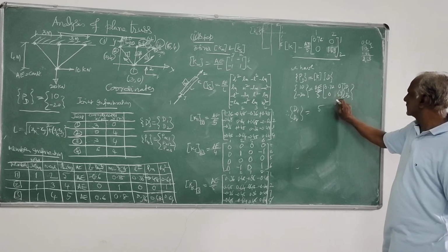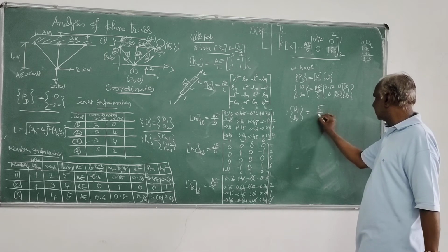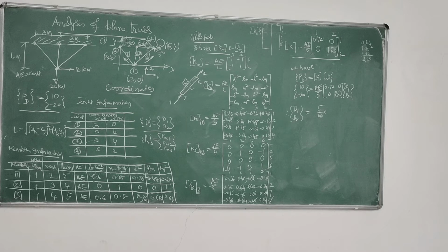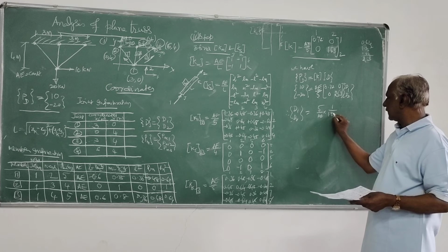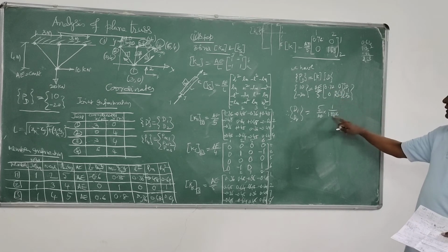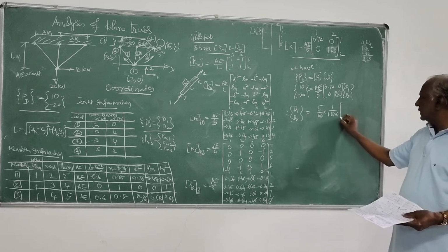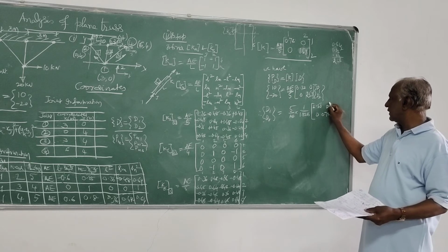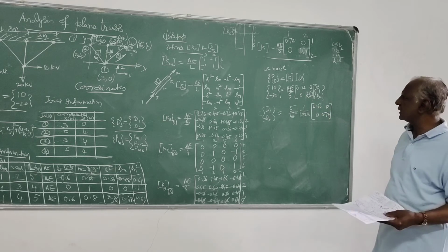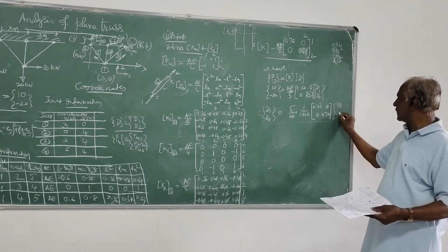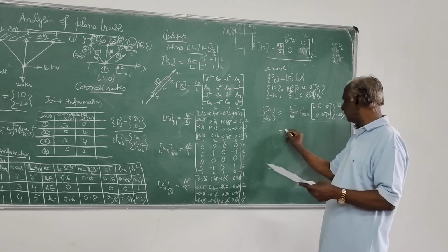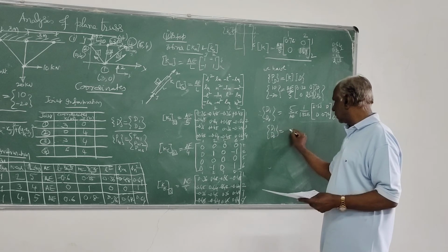Therefore D1, D2 is equal to this. That 1.53 is 2.53, sir. Okay, so 2.53. Yes. This is 5 by AE into the inverse of this matrix. You can find the determinant: 0.72 into 2.53 is 1.8216 minus 0. That's the determinant, 1 over 1.8216, you can cross check. I will leave this column: this will be 2.53, this will be 0.72. This is the inverse of this matrix into this 10, minus 20. D1, D2 is equal to this inverse into this. This inverse I have determined.